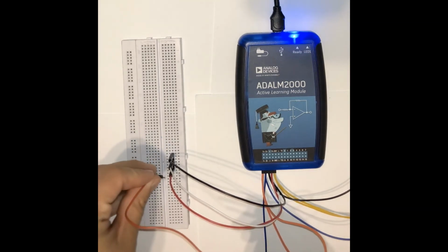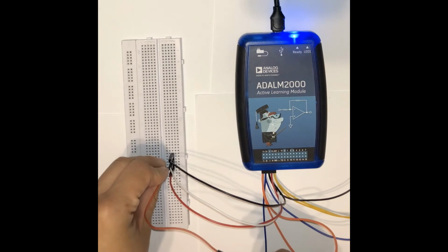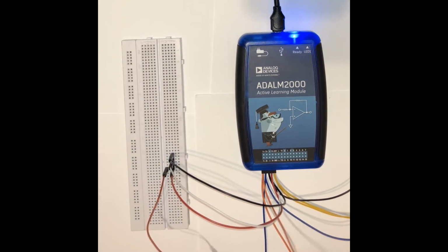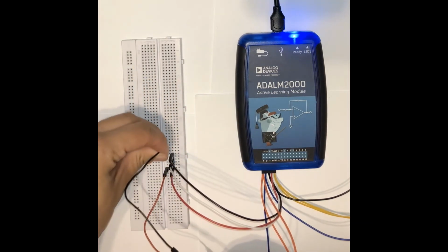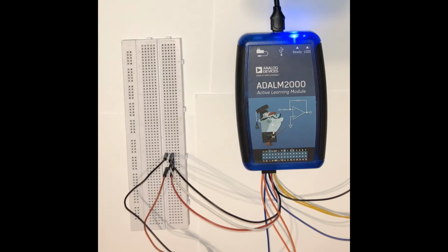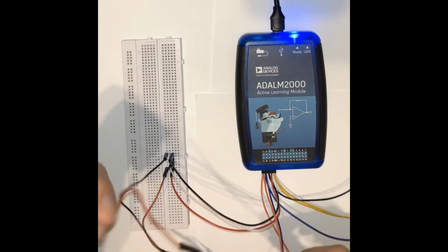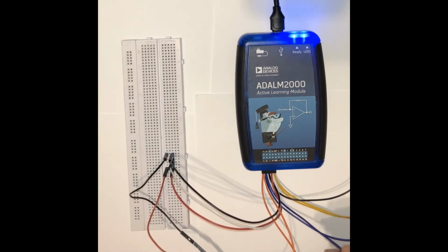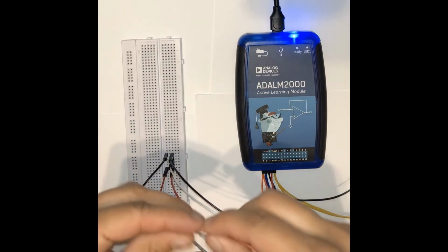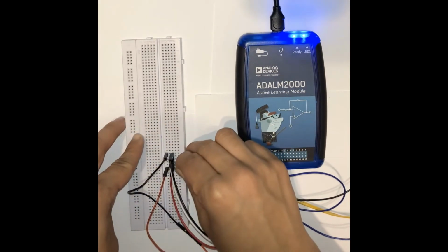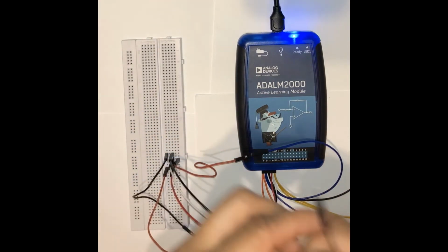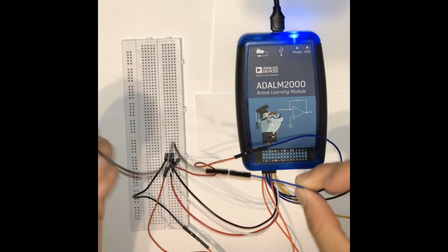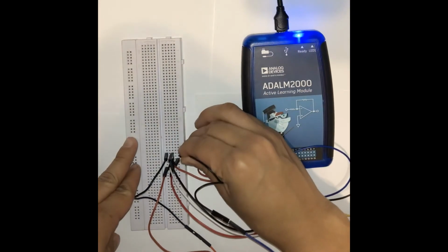And so then we'll connect these across the power supply wires so that we can measure and confirm that that voltage is being delivered to the breadboard. And you must ground all of that too so that you can get an accurate measurement of the voltage. And so there, we'll do the white lead as well on channel 2. You have to ground that as well.